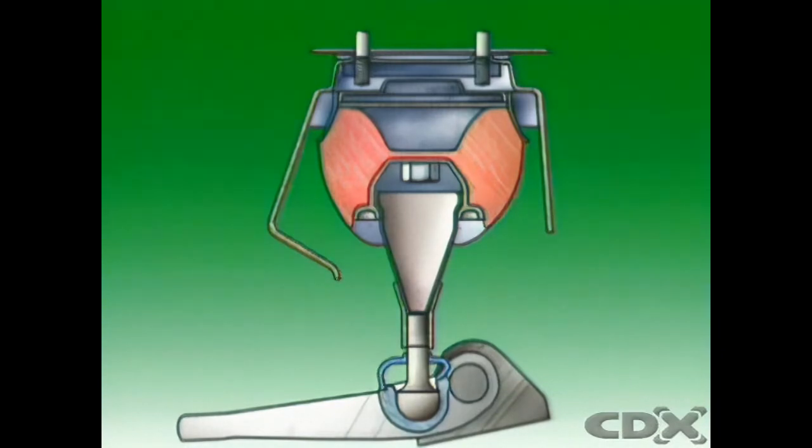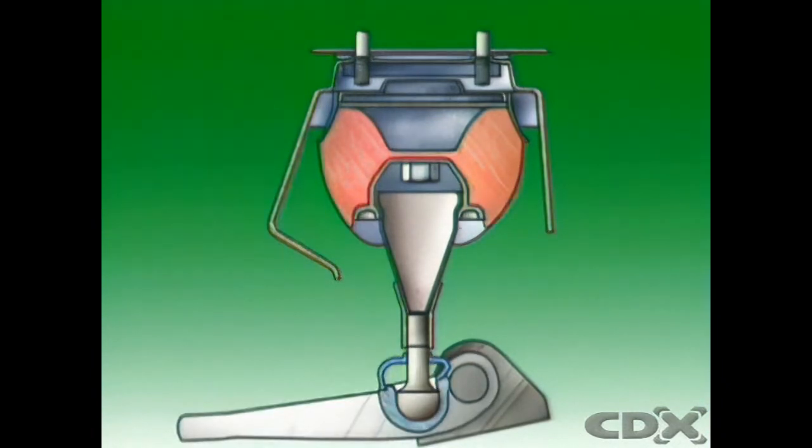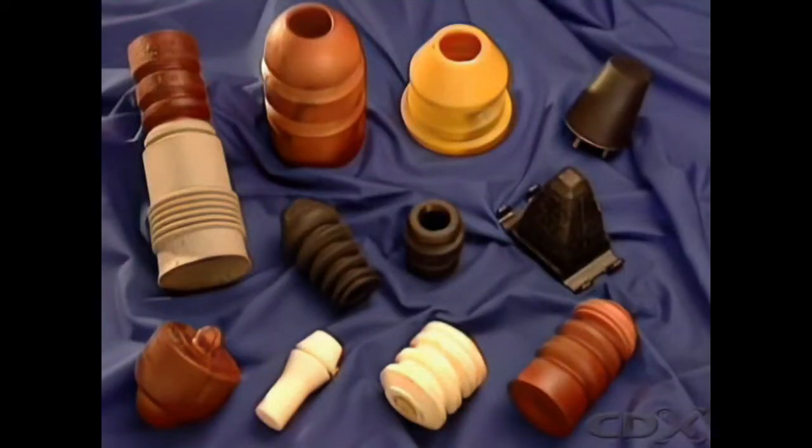This rubber cone is the vehicle's main suspension member. Increasing the load on the suspension causes the cone to act like a spring being deformed. When the load is removed, the rubber's elastic properties tend to return it to its original state. Rubber has a number of advantages. It doesn't need to be lubricated, it can be made into any shape as required, and it's silent during use.